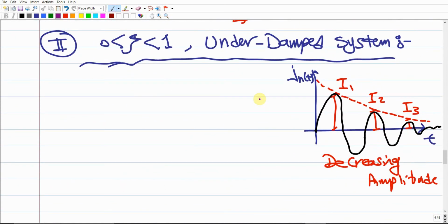But for example, with the underdamped system, if there is a bump in the road or a corrugated road, you're going to vibrate for a while and then it's going to suddenly stop. It will reach the steady state very quickly through some damping in the amplitude. You start with very high vibration, then this vibration decreases. And this is preferred in some applications, like the suspension system of the car, which is preferred to work under this condition all the time.